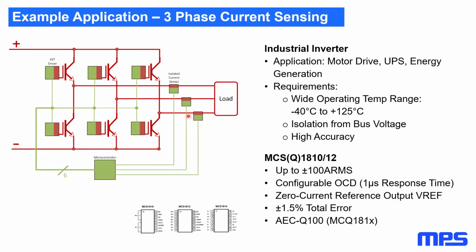You can just design your PCB so that it's huge and your current carrying traces are on opposite ends of the PCB, but that's not practical. The better way is to just make sure that your current sensors have differential sensing pairs in there. And now you can put the same current sensor on all 3 phases and don't have to worry about interference.